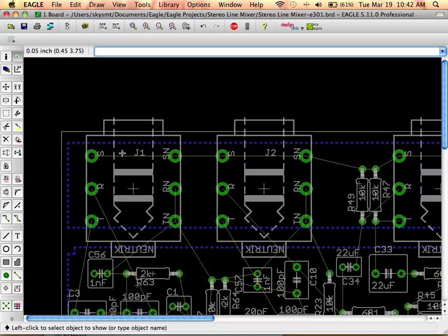And the reason stems from the fact that wires exhibit non-zero resistance. So when you plug into ground at one end of the room, and then you run cabling from there over to another end of the room, the ground conductor, because it carries return current, has a small voltage drop across it. And the return current is AC, it's sinusoidal at 60 hertz.